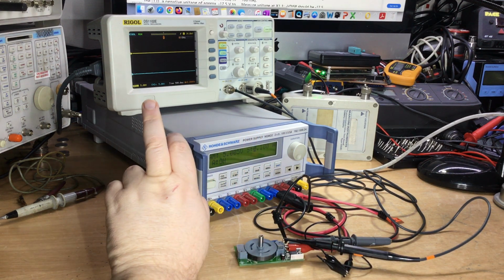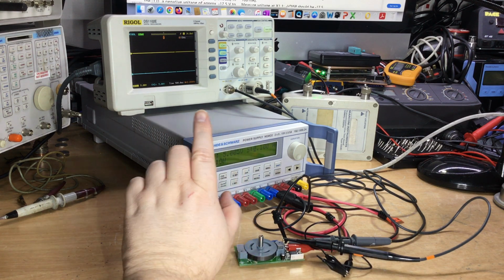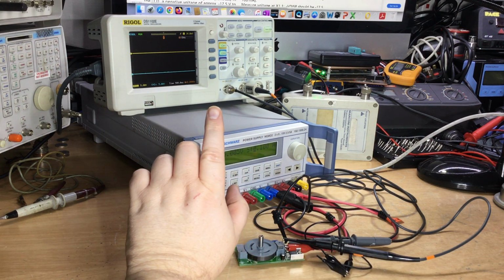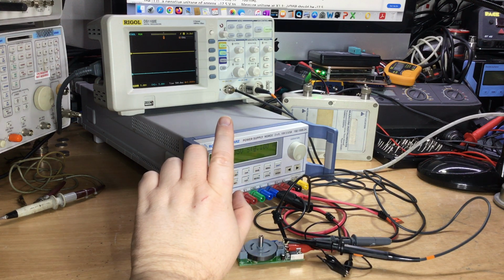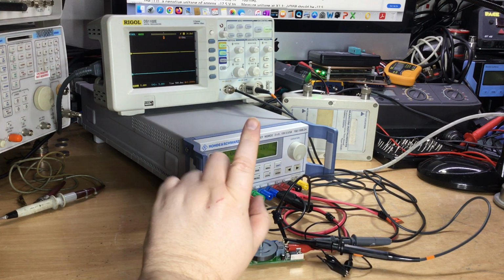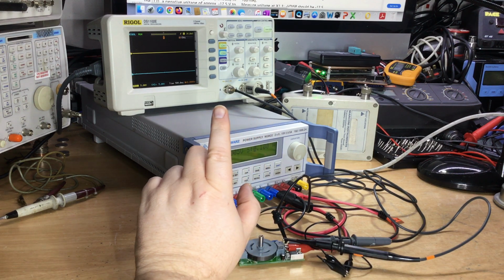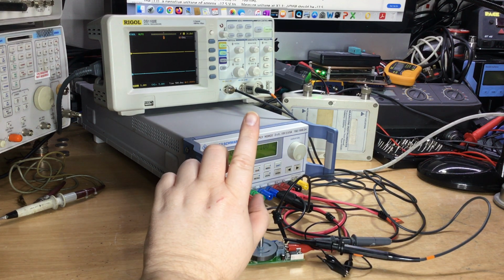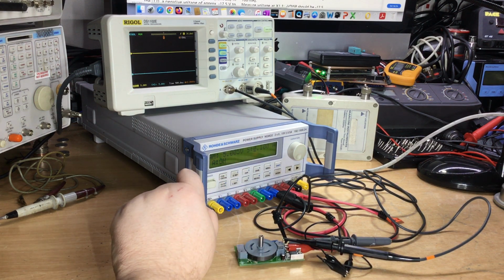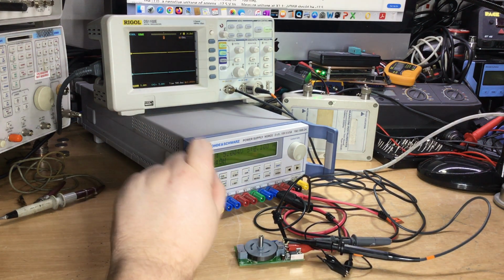So we've set the power supply to 5 volts DC at 100 milliamps maximum current in case of any shorts, any smoke. And then on the Rigol scope, I've set that up so that it's DC coupled at 5 volts per division, and on both channels 1 and 2. Obviously channel 1 goes to one Hall effect sensor, channel 2 goes to the other. So we'll be able to look at the waveforms on there.